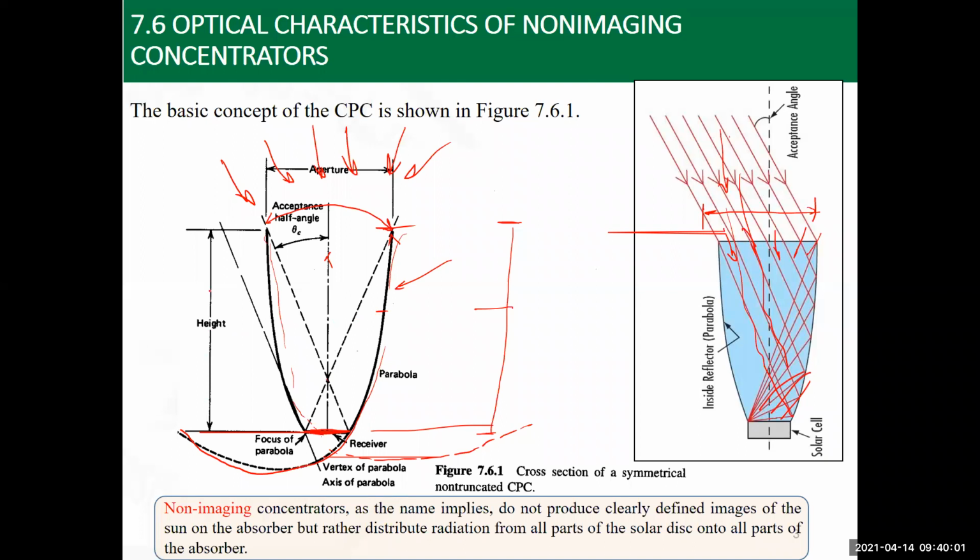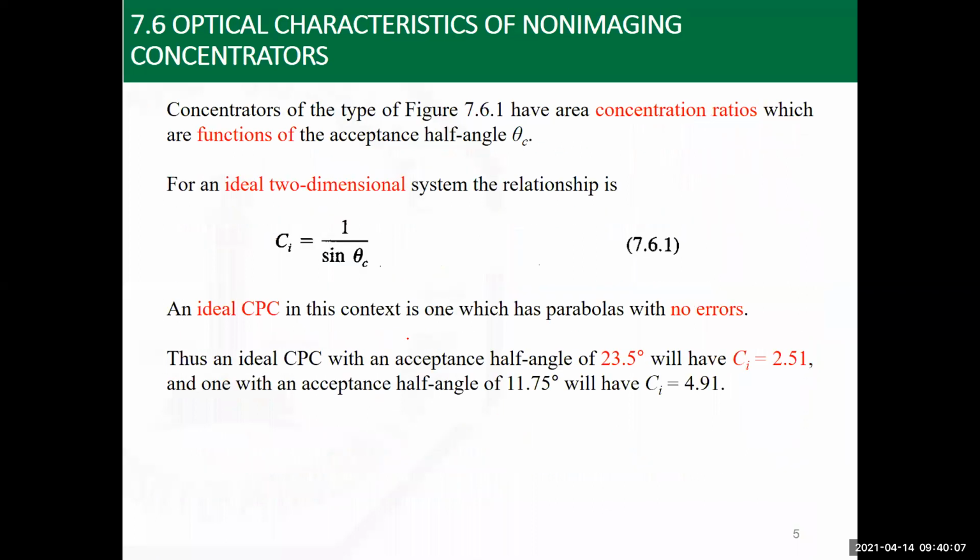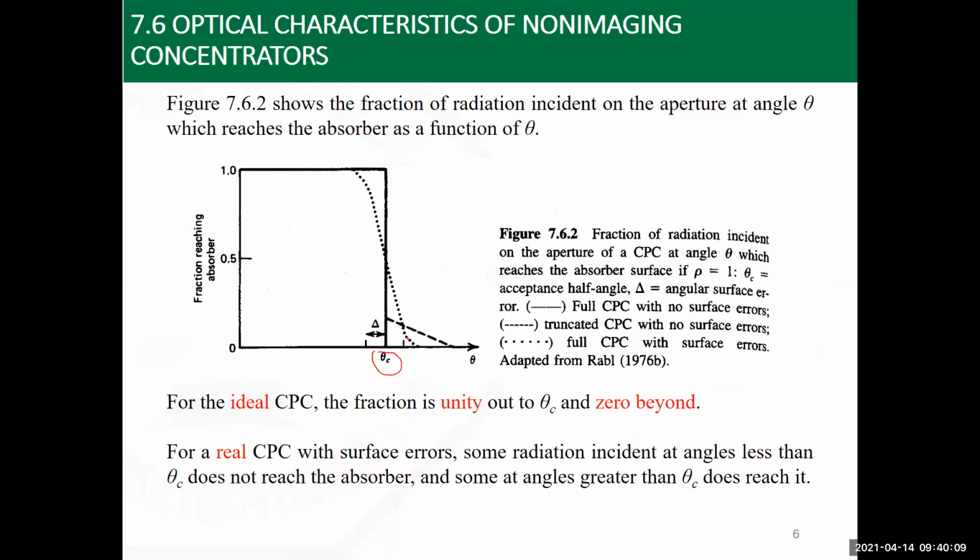So they don't go for the whole height, but for a fraction of the height, and it's a truncated collector. And this is part of what you can see here: if you are talking about a truncated collector with a CPC, you can find that you can still get some radiation falling onto the surface, even if you exceed the value of the acceptance angle.